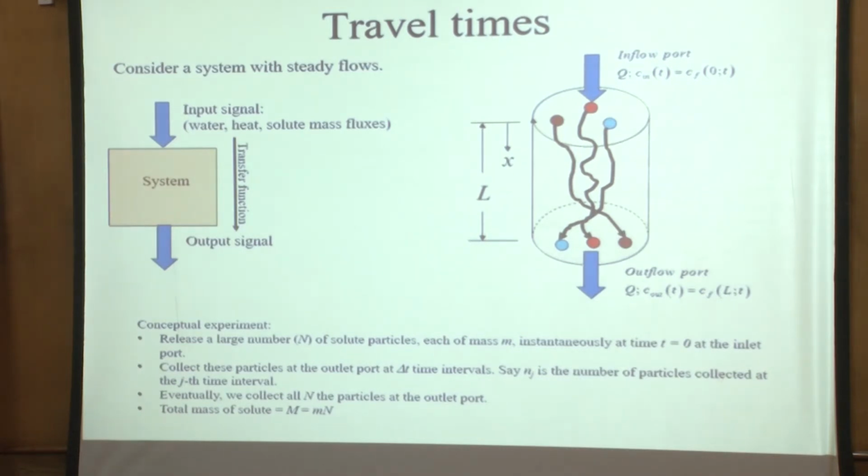So what we now want to do is sort of use a different conceptualization. Let's say we still have that soil column. Okay, this is a sketch, and this is the inflow. We will assume that the flow rate is steady. So Q, the total volumetric flux through the soil column, is steady. It's not changing with time. So Q is the amount that's coming in. What is entering at this is a certain amount of solute, which is our flux concentration at x equals 0. And at x equals L, what we collect is the flux concentration, which would look perhaps something like this.